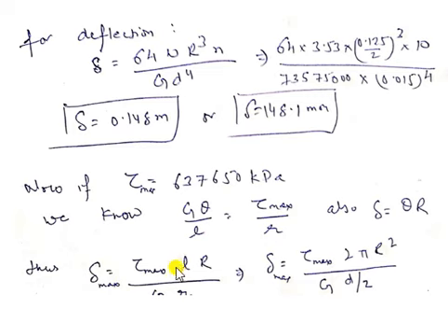Now what is this L? L is the length of the wire of the spring. Now length of the wire of the spring, you very well understand, it could be written as the circumference of the turns, and you know the circumference of the turn can be calculated, so L will be equal to 2 pi capital R into n. Okay, so this L equal to 2 pi capital R n should be substituted over here.